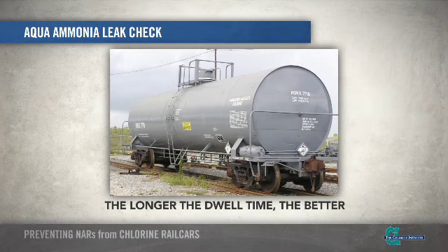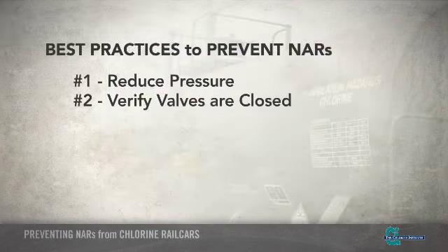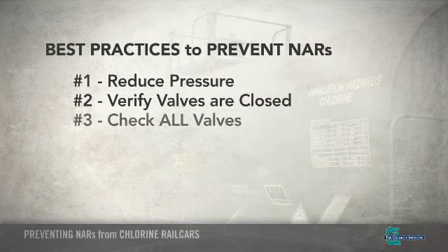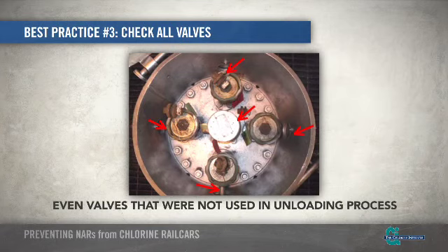Some shippers let the car sit up to 24 hours prior to shipment. Best practice number 3. It is important to leak check all the valves on the car even if the valves were not used in the unloading process. Several NARs were reported where the leak occurred on a valve that was not used during unloading.